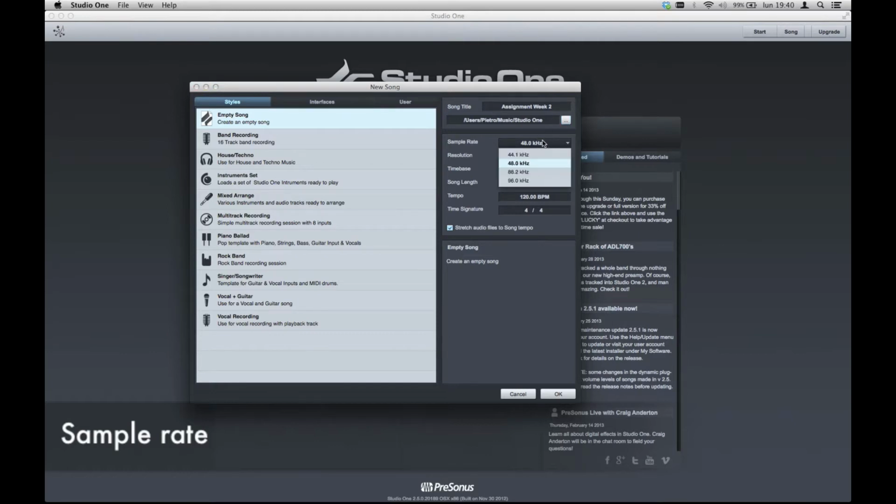The sample rate is how many times per second the AD converter reads the analog signal values and converts them to binary values. So analog to digital conversion is a discretization of a continuous signal. With high sample rates, you get more accurate sampling. Most audio interfaces let you choose between 44,100 Hz, 48,000 Hz, 88,200 Hz and 96,000 Hz, while on professional equipment you can reach up to 192,000 Hz.